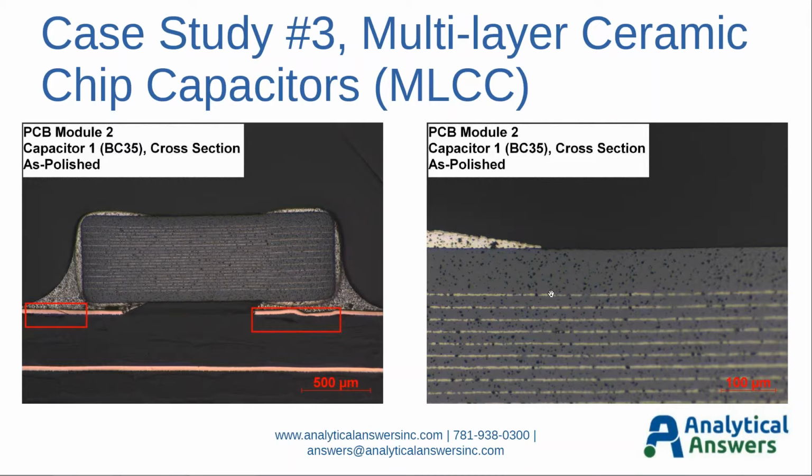This is just a higher magnification view, partial view of the MLCC. We can see, again, no chip outs at the interface here between the MLCC and my mounting epoxy. Nice, flat, and smooth. The black dots that we see in this image are intrinsic to this particular MLCC, and not from the polishing process.